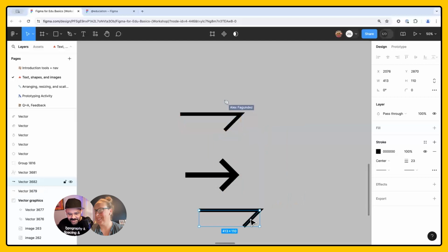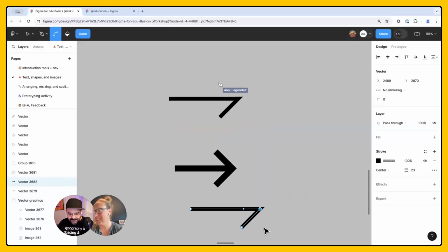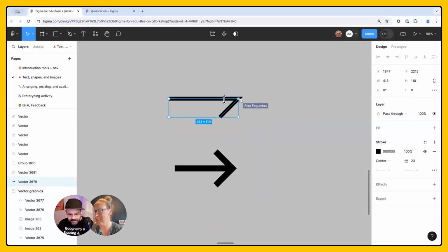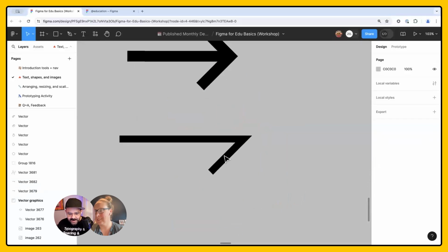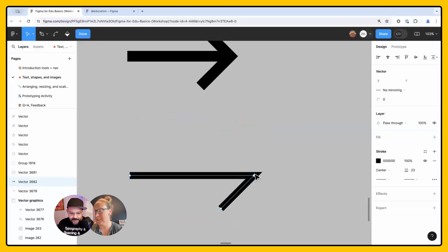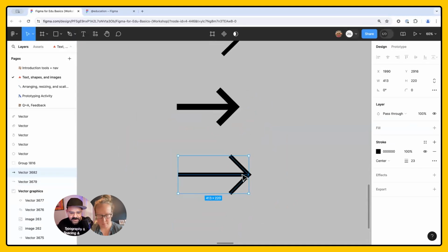I'm going to duplicate yours and I'll show everybody where you're at and how to get from that point. So here, I'm at your arrow. I double click. I see that point. I press the pen tool. I click on it. I hold the shift key to drag it out. And you'll see that it snaps when it hits a nice even point. I click that point there. If the line is still sticking, I press the escape key and I can press the escape key once more and I exit out of that graphic.